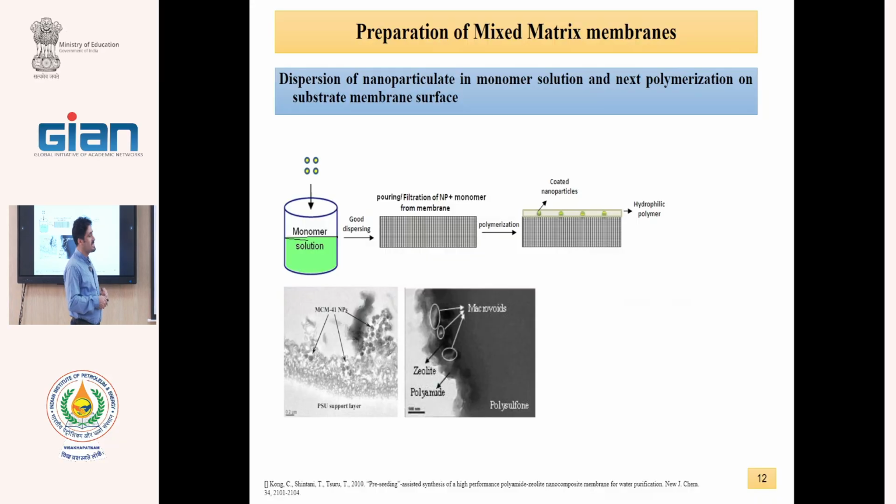For increasing the stability of the nanomaterials, after coating of the nanomaterials by self-assembling or by filtration, we can use an adhesive. We can use a polymeric layer that protects the nanomaterials from detachment.